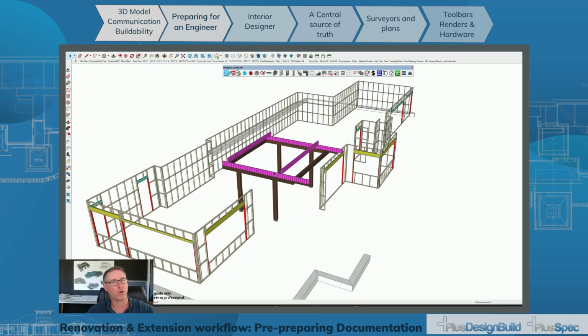But I also asked what I required when I lodged those plans, and they told me, and you're going to find the same thing. So speaking to your local authorities first about what you require to lodge plans will get you one step further. In this case, I was told that I'm going to need engineers, I'm going to need a builder's license. Fortunately, I'm a builder, or an owner builder's license if you're not. The engineer needed a geotech report. But I didn't really want to get a geotech report first, so we had to make some assumptions up front.